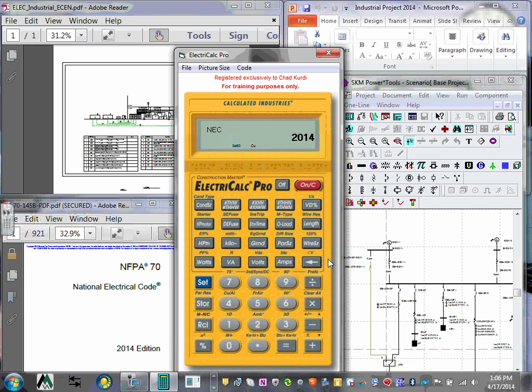I put a couple on my YouTube channel, a bunch of calculators, and it's called electrical calc. It's really great, easy, the fastest thing. That's what I like about it, especially in sizing conduit. Say you have 4 feeders, 500 kcmil THHN, and another one for 350 for the neutral and the ground, all different sizes. What size PVC conduit do you need, or rigid, or EMT? A couple of clicks, you're there.